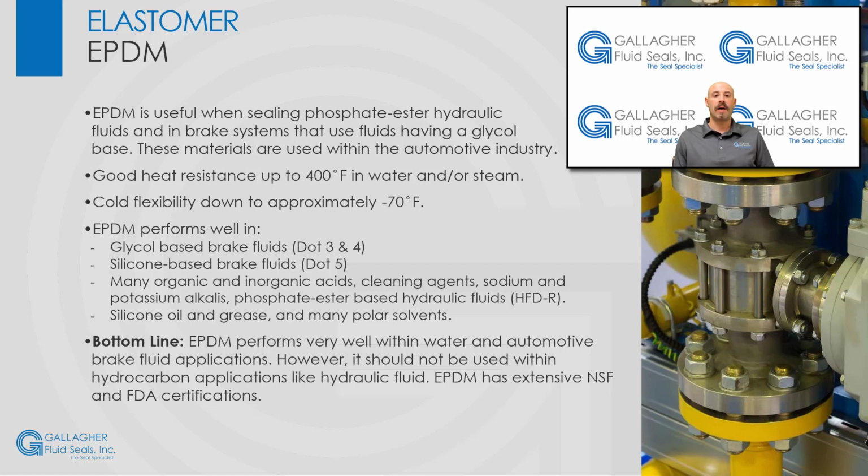EPDM is not compatible with the following: mineral oil products such as oils, greases, and fuels. The key takeaways here are that EPDM performs very well within water and automotive brake fluid applications. Additionally, EPDM has extensive FDA and NSF certifications. EPDM should not be used within hydrocarbon applications like hydraulic fluid, as the material will swell and ultimately fail.